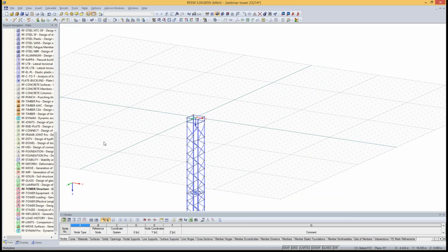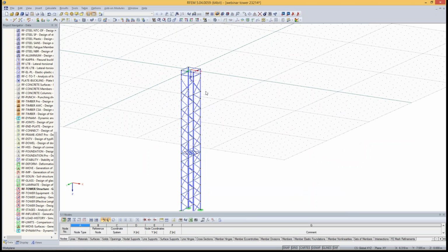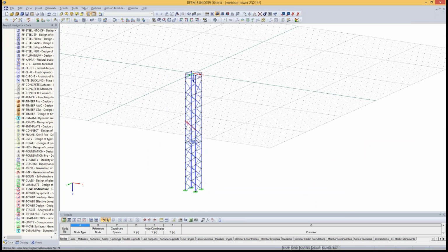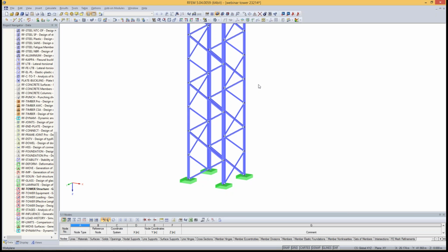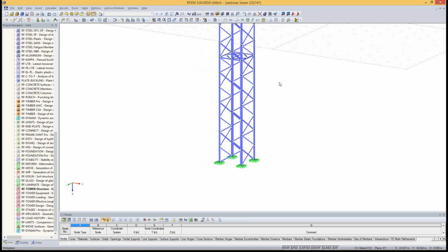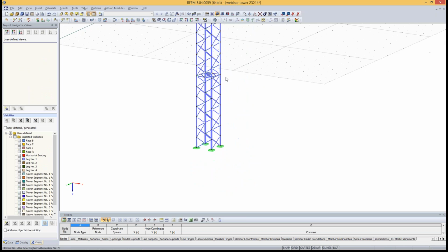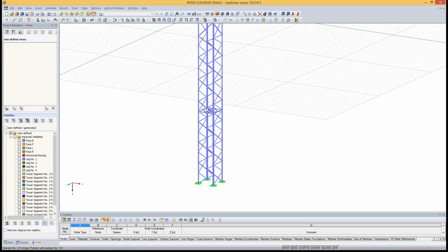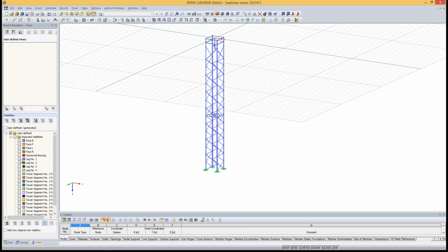Good. So now, as you've seen, I've exported the tower to RFEM, and to do it manually, it would take a lot of time to define all the members step by step. Another advantage of tower structure is that it automatically defines also partial views. We will see in the design of the structure later that you can check utilization ratio easily if you use these visibilities.